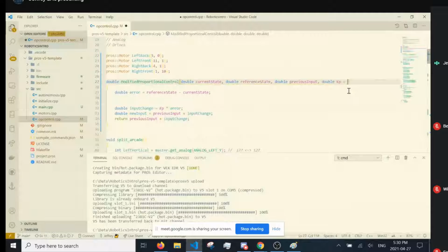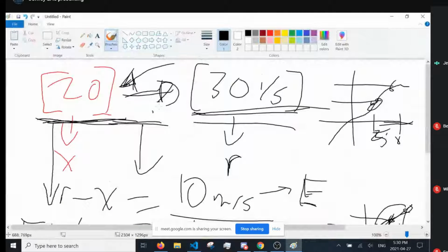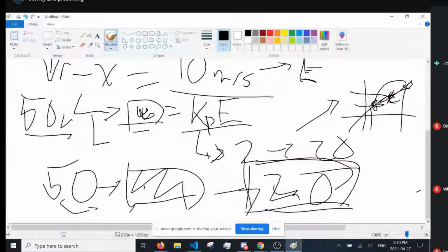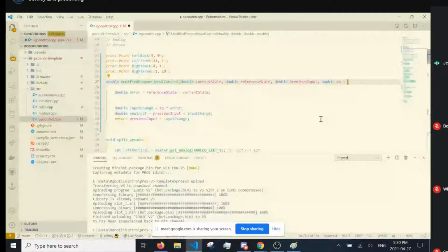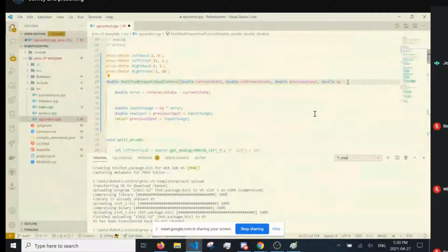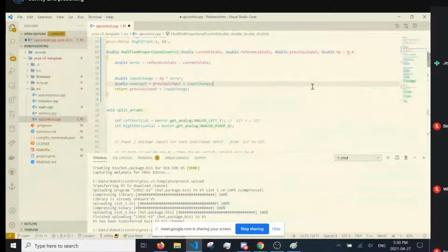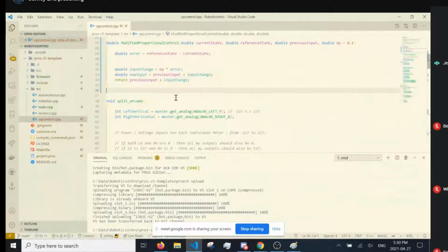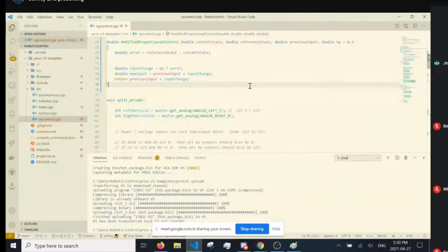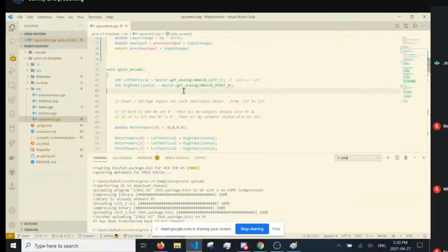Anyway, if I take this code, for our proportionality constant, in the case of direct proportional control, you want to make this relatively high based on what units you're using and stuff like that. This is something that you just tune on your robot through trial and error generally. In this case, because I'm taking this as a sum over time, I'll make it kind of small so that I don't blow up my robot, just in case. I actually don't know what a good constant is. 0.1 sounds okay. Does it sound okay? Yeah, I guess it sounds okay.